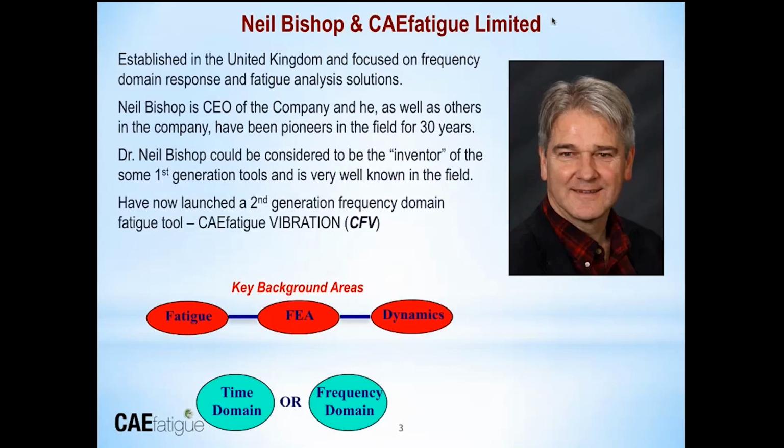So as I said, my name's Neil Bishop. I'm the CEO of a company called CAE Fatigue Limited. And I spent most of my working life thinking about the issue of doing frequency domain analysis and how it compares to time-based calculations. Inevitably, those kinds of questions fit into the framework of doing fatigue analysis with FEA codes. And then it's mostly relevant to the case where dynamic response is important or resonance is possible within the structure, but not exclusively. These methods also are perfectly applicable for static problems. So that's something I wanted to make clear.